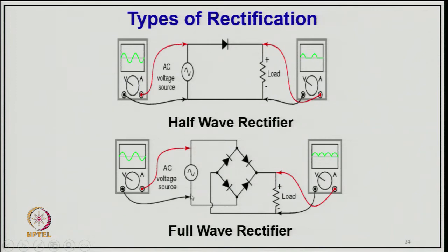But if it is typically positive, then it will go through this same terminal and return back from this terminal to this one. So, this diode rectifier provides the conversion from your AC to DC in both half cycles, and you get across this resistance a voltage that is all the time positive only. Of course, you will get a ripple voltage, but it will always be positive because of the rectification provided by the diode.